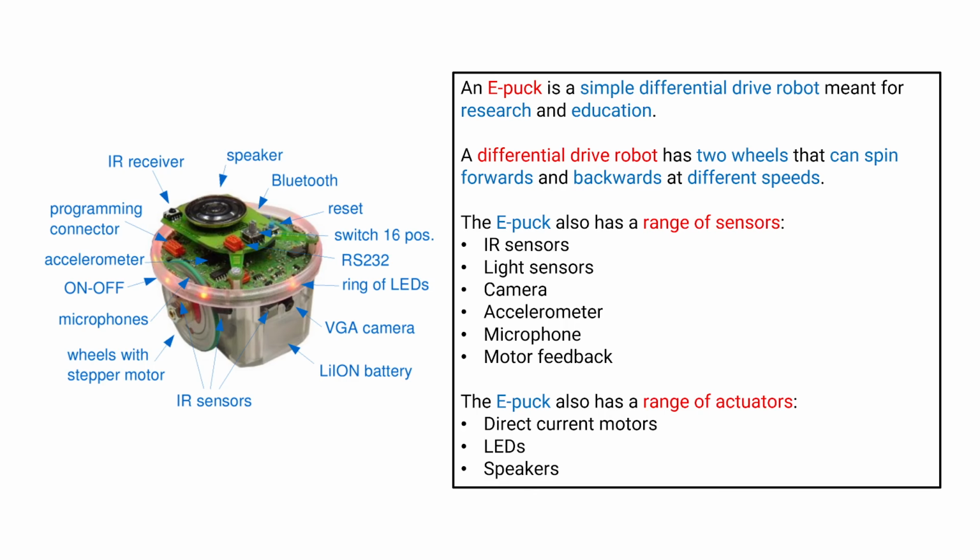So you might want to have other sensors in there. The original Braitenberg vehicles, the idea was that they had light sensors. So there are light sensors on here that can sense the intensity of light impinging on that sensor. And then there's also a more sophisticated actual camera. So if you want to take actual video, the infrared sensors can detect proximity, but the video can detect a whole range of other things, maybe what the object is, what its type is, or maybe even just simpler properties like what color it is, things like that. So those are things that the robot might use to identify the object more than just where it is.